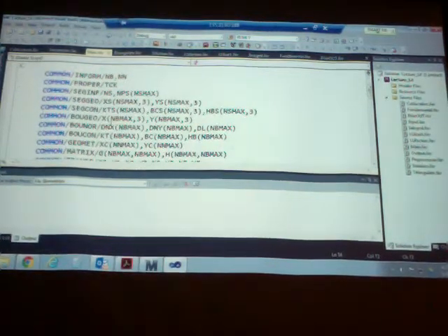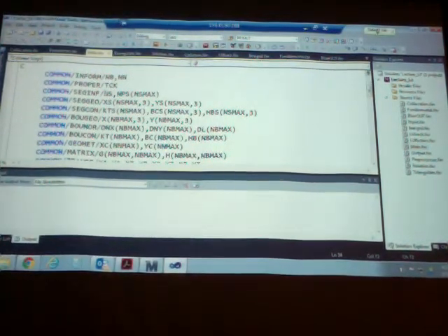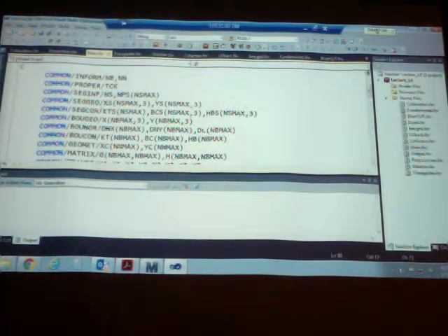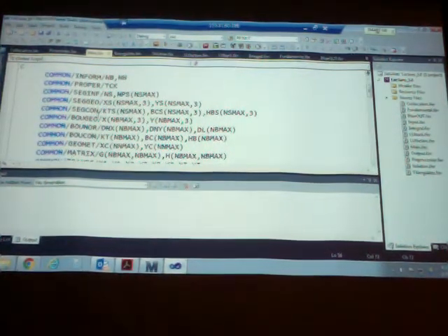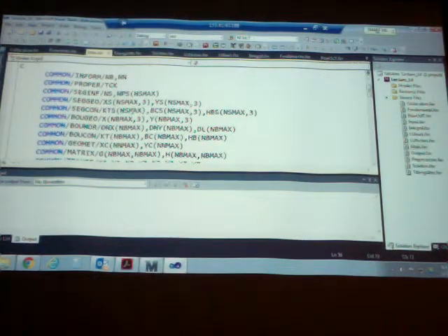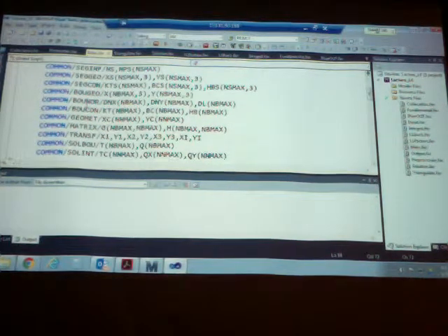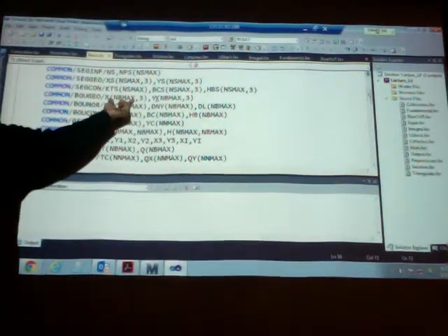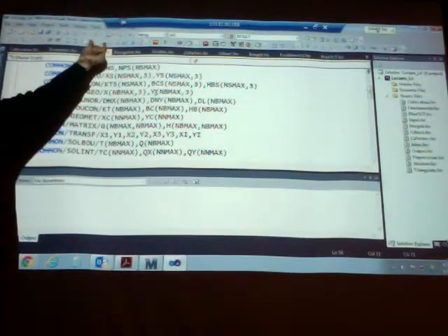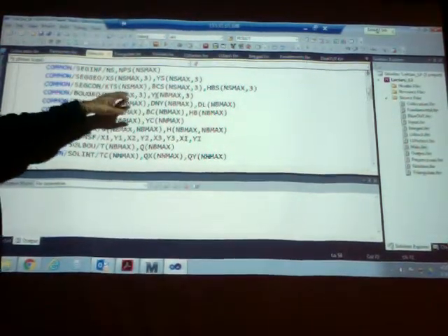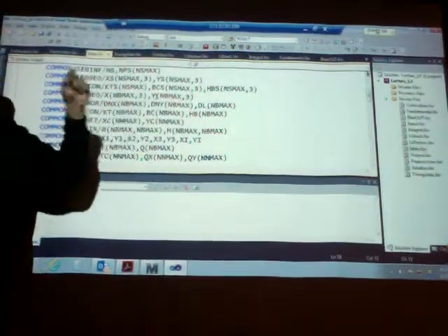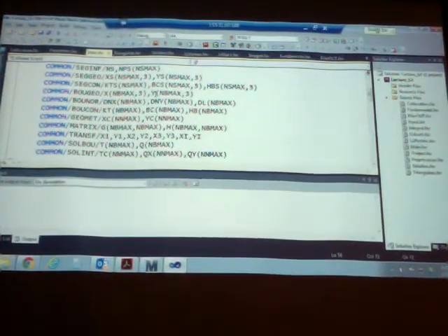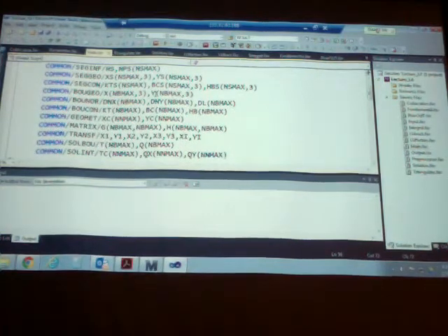All right, so more information is, for example, the segment information, the splines for pre-processing, the geometry of the splines, the boundary conditions on the spline, then the boundary information. The preprocessor routine is going to take that spline information and generate boundary elements, and remember the coordinates of the boundary elements. You have as many as MB max boundary elements, and you're going to have as many as NB in a particular application. And every boundary element has 3 locations: first point, second point, and third point. Okay? There are 3 nodes that describe a boundary element.